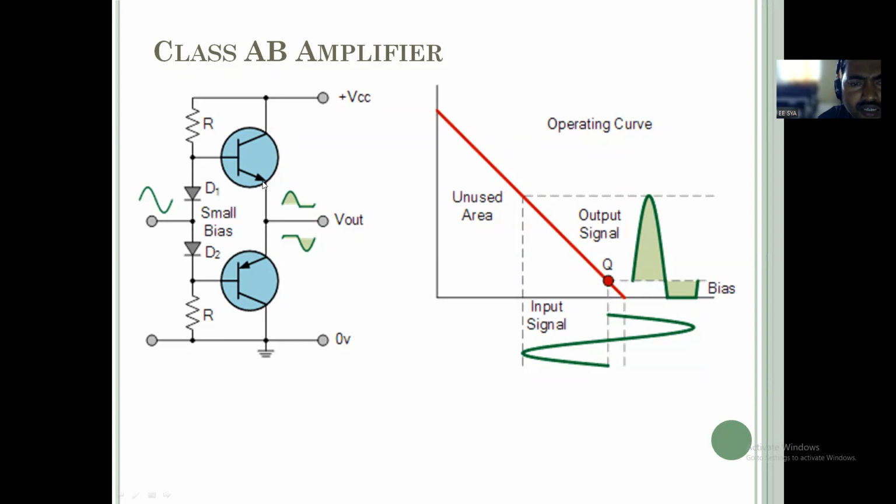त्यामुळे काय होतंय, during the period of the crossover there should be whatever the power required for your transistor that should be provided to this type of the diode, right? So that's why during the period of 0.7 volt to the -0.7 volt, during the period of -0.7 diode D1 is on, so it should provide the voltage to the transistor, and during the period of the +0.7 diode D2 is on, so it should provide the voltage to the transistor. So during this period, this is the crossover distortion period.